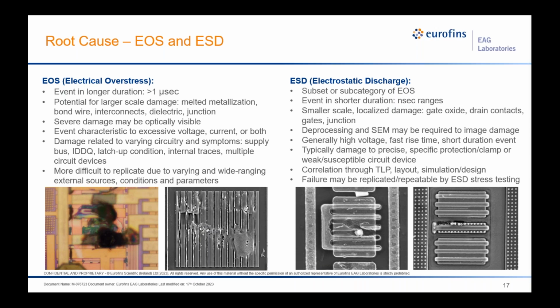If it's an ESD, we have an entire ESD department with multiple sites to help replicate some of that on the different types of ESD testing, latch-up testing, and also the TLP characterization to see if your ESD diodes are actually doing what you think they're doing. Especially if you don't have a standard cell library kind of device.